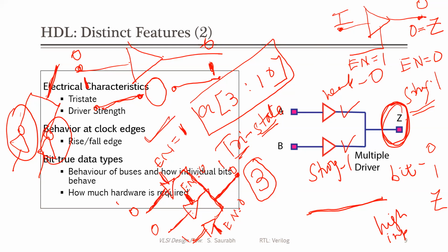Why? Because in a CMOS circuit, the output is always connected either to VDD or ground through some low resistance path, at all instants of time in a static condition. So what can be the problem in this configuration?